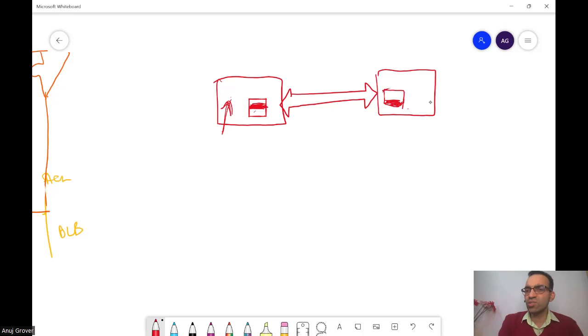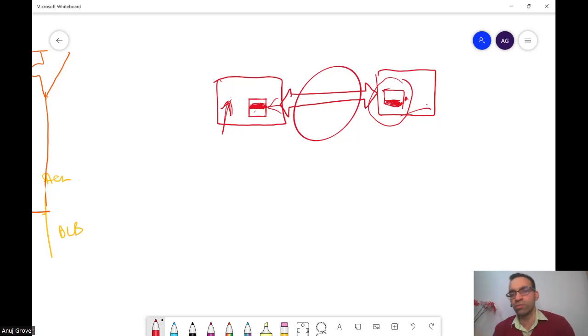Because this core will not usually need to access this part of the data, let me just write a dirty bit. Transmitting a dirty bit is much lower power for the bus, is also faster for the bus, and also over here I save dynamic power because I'm just writing one bit, not all the bits of the word. So I save overall power, and I also save transmission of all this data, and therefore probably one cycle also.